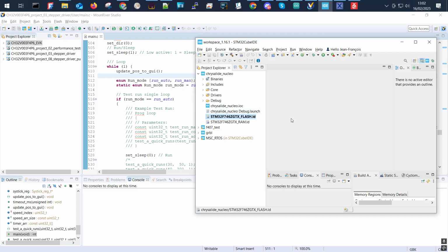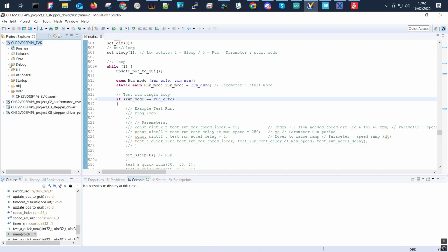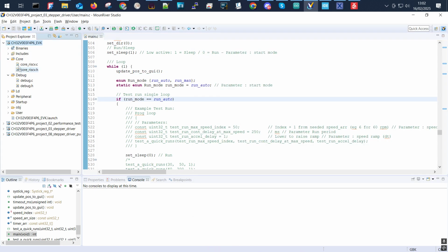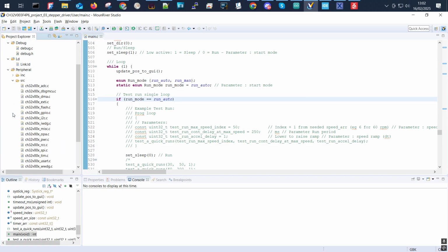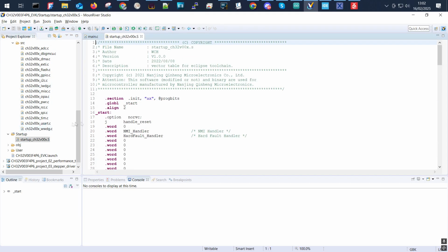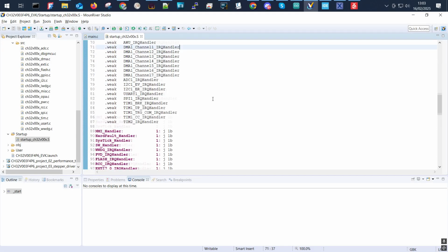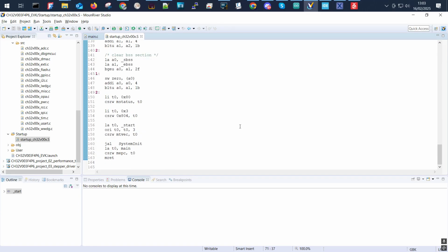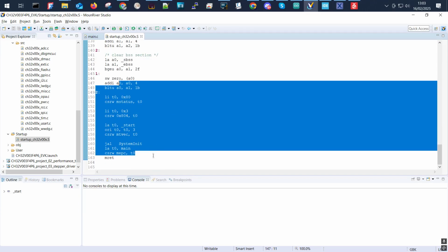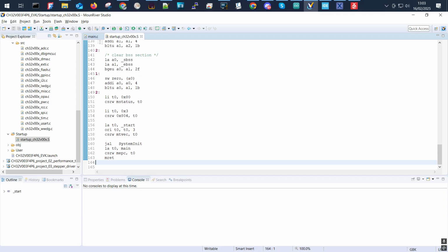And the boot itself can be simple or use multiple steps. It can have a bootloader, and can run code from RAM if we don't want to flash the program and stand in RAM. We see we also need a couple of libraries, peripheral libraries. There is a startup procedure, a startup file. This one, for example, is an assembly file actually. We have the addresses of the interrupt request handlers, a little bit of manufacturer-specific code for startup, but this doesn't need to be changed.